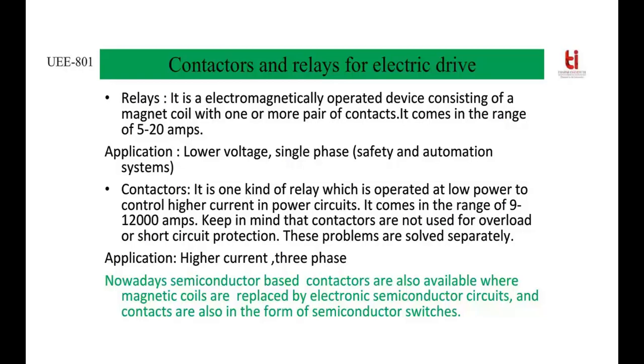One thing to keep in mind is that contactors are not used for any protection, like overload or short circuit protection. These are just used to give a path to the current. When it is closed, current will flow through the circuit. When it is off, it is open, and then current will be blocked. So overload or any other protections have to be solved separately.